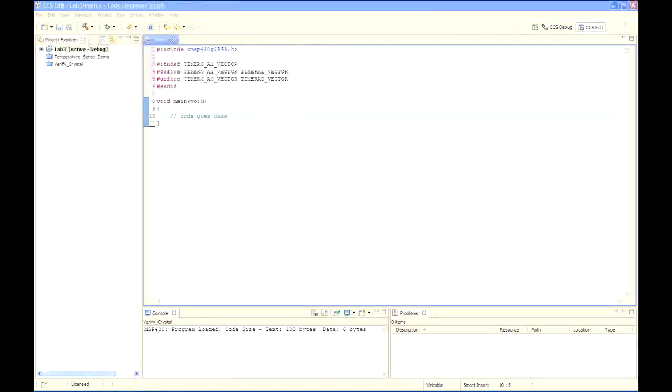So what we're going to do first, we'll initially start this lab by running the CPU on the VLO. That's the very low frequency oscillator. This is the slowest clock, which runs at about 12 kilohertz. So we're going to visualize that by blinking the red LED slowly at a rate of about once every 3 seconds. We could have let the clock system default to that state, but instead we're going to set it specifically to operate on the VLO. This is going to allow us to change it later in the exercise. We're not going to be using any clocked peripherals in this lab exercise, but you should recognize that the A clock is being sourced by the VLO.